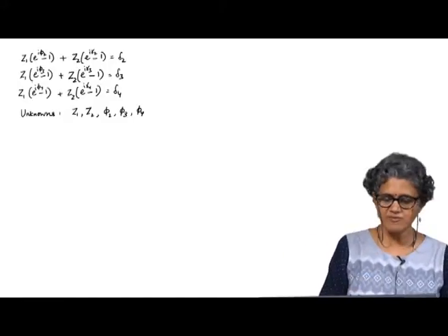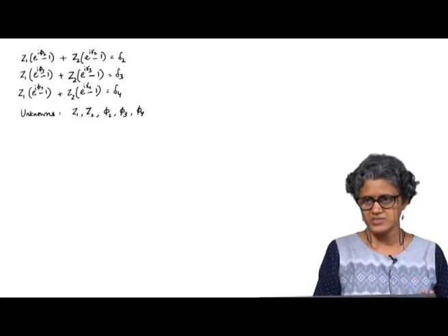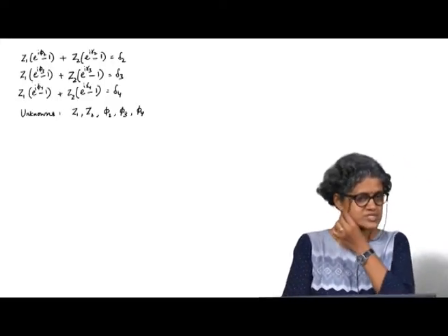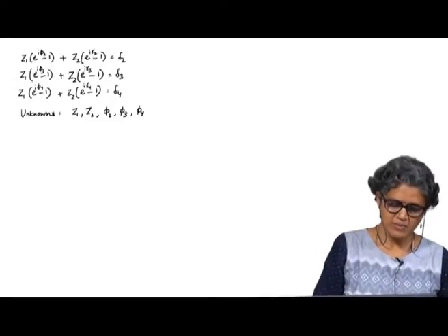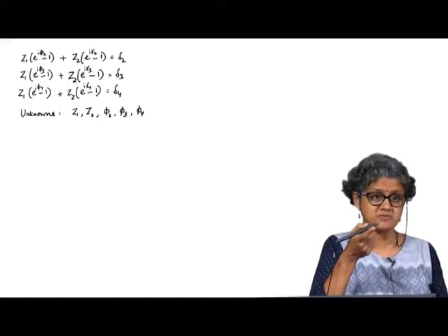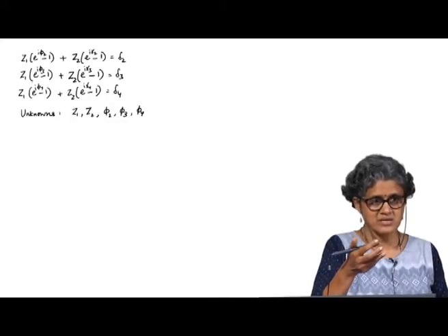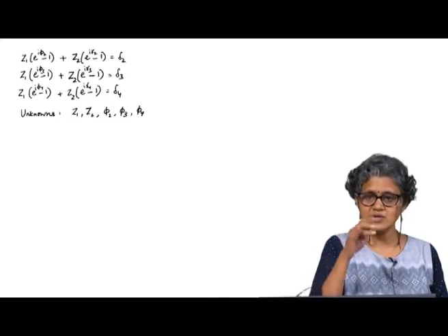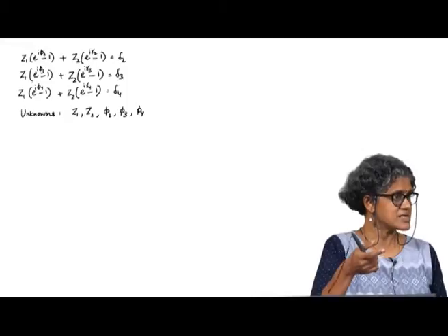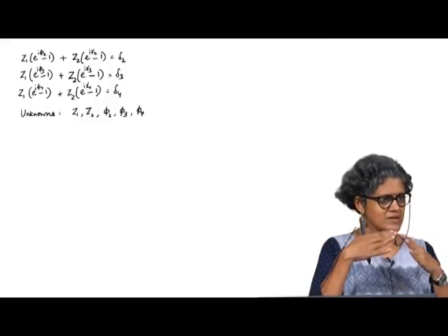You do not have that for up to 3 positions. We saw we got a nice set of linear equations that we could solve for the dyad. Now, that is no longer the case. We saw that even in the case of specifying the fixed pivot, even for the 3 position problem, you have to satisfy a compatibility condition, which is transcendental in form. And we did that using geometry, forming that triangle.